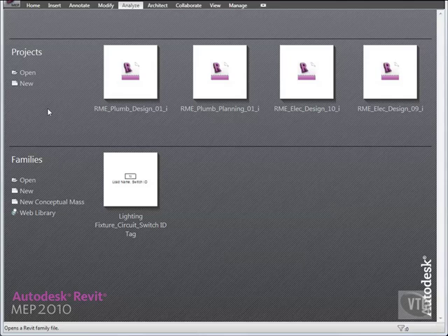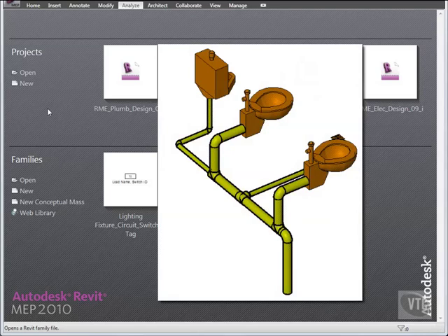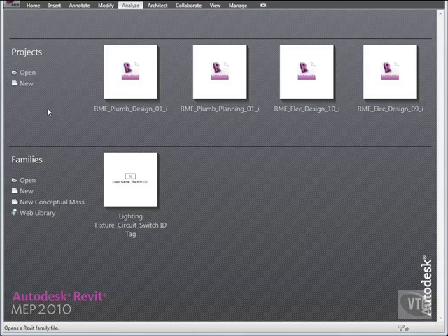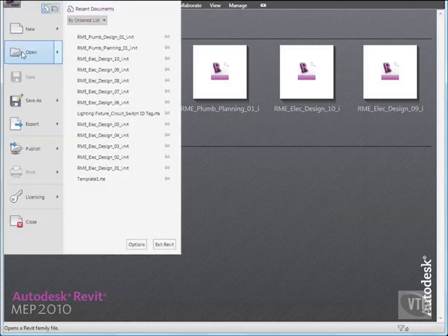In this lesson, you will create a sanitary system consisting of the toilets, a urinal, and a floor drain. You will then use Revit MEP's Layout Path tools to create sloped piping to connect the fixtures to a sanitary outlet. Click the menu browser and select Open.